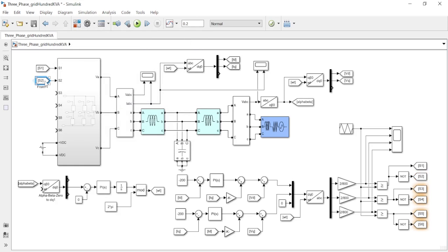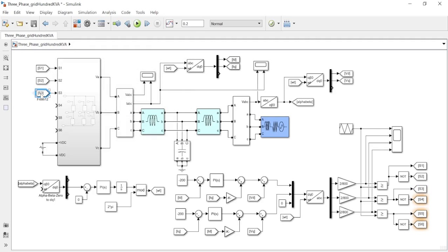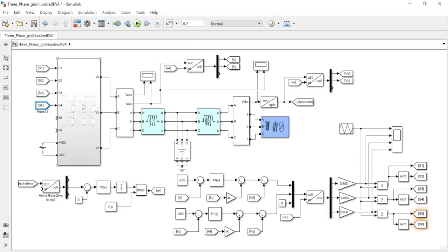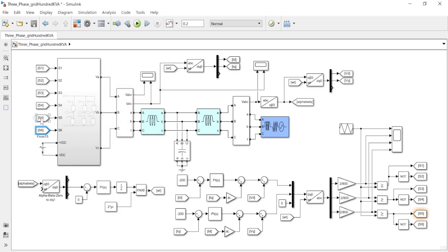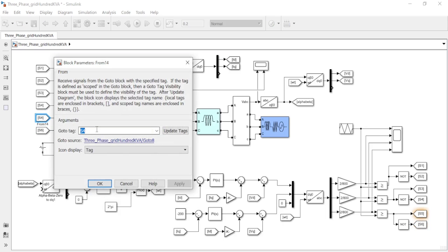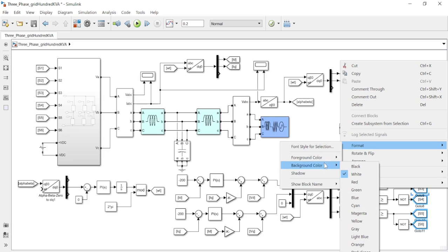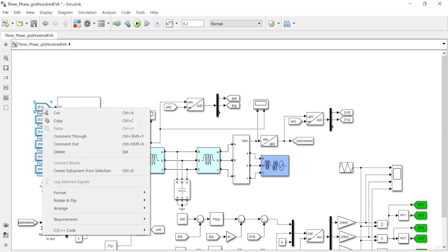So as you can see from this system, we can't just get the parameters just like that. Since we designed a 10 kVA with L1 equal to 9, it doesn't mean that we're going to have L1 as 90 and the system is going to work. No, this is a non-linear system, and most of the parameters, even the PI controller, also had to change accordingly.